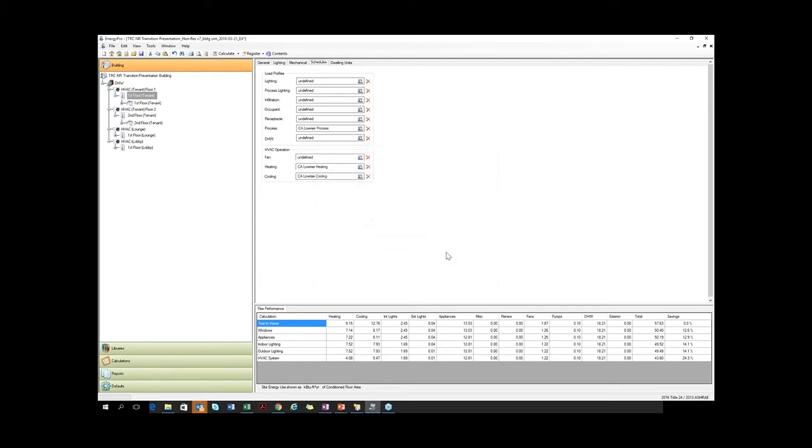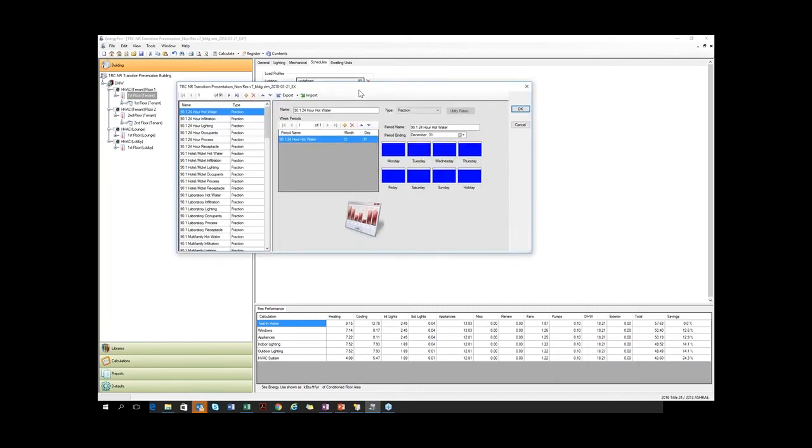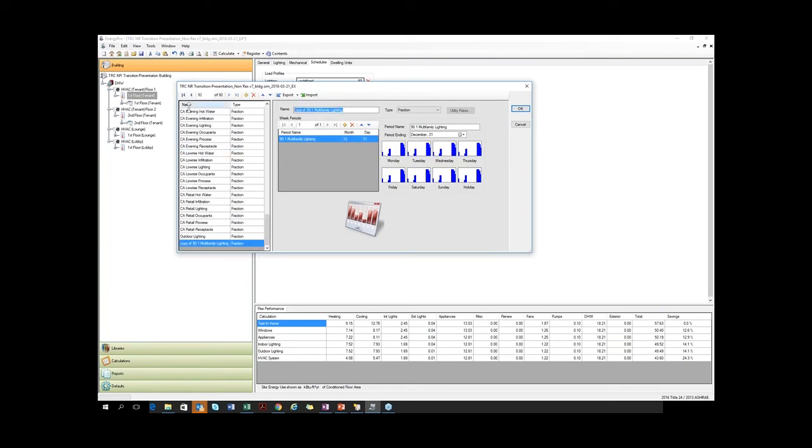The final schedule that we're going to change is a custom schedule for the multifamily upgrade program, and that's lighting. So I'm going to come in here and define it one time with you guys, and then I'm going to update it for all of the zones. So what I usually do is I start with the 90.1 multifamily lighting because it's most similar to that. Make a copy. Label it like multifamily upgrade program.